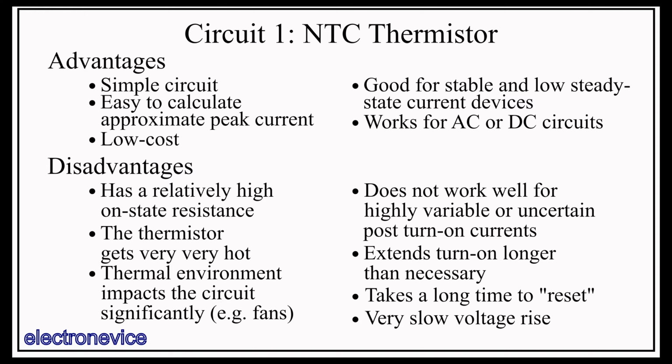Tying in with this is also the fact that the thermal environment impacts the circuit significantly. If you insulate the thermistor too well, you might start a fire. If you heat sink it, or even if it's incidentally in the path of a fan intended to cool something else, it will be cooled down significantly more, and thus won't get its minimum resistance, resulting in burning off even more power. While I was testing these devices, I put a little shelter around the thermistor because I noticed that even when I just moved around the room, I got a noticeable change in the measured resistance. A fan blowing across the thermistor would have had a much greater effect.